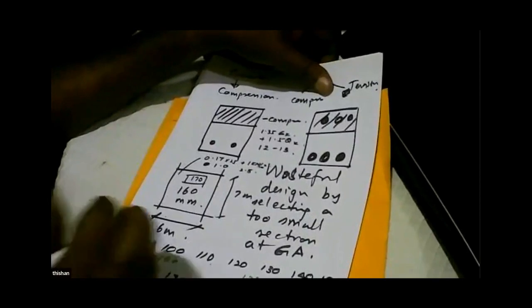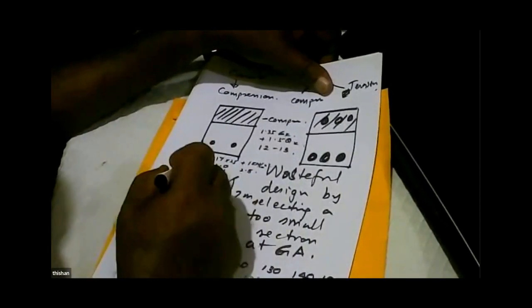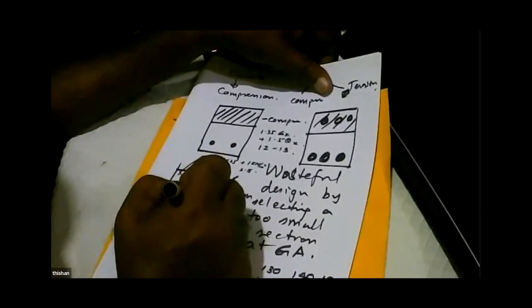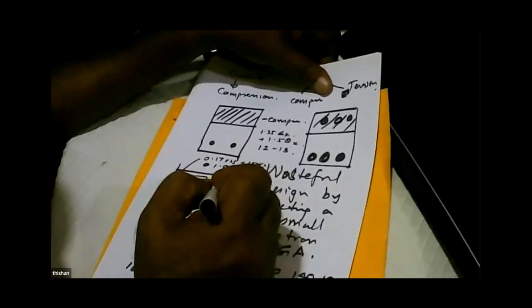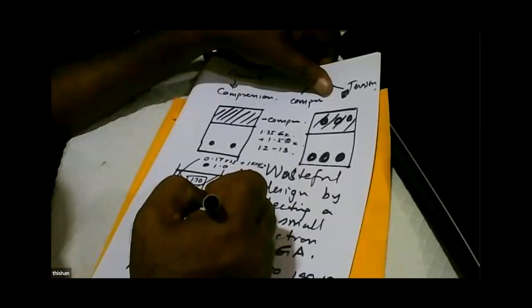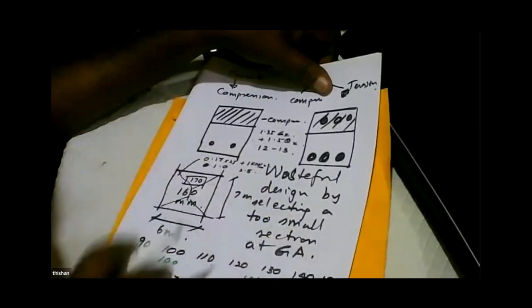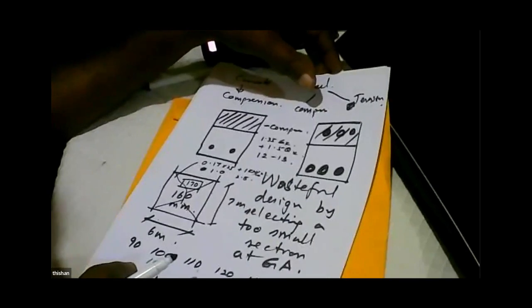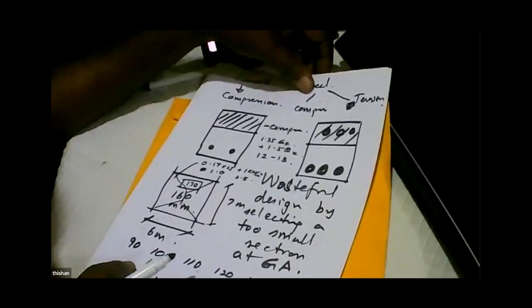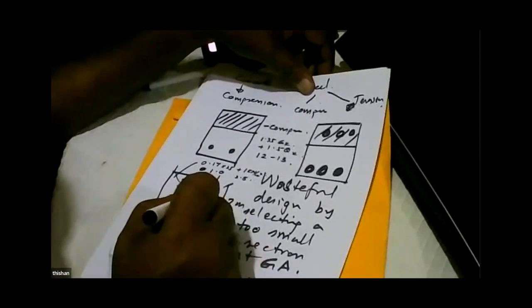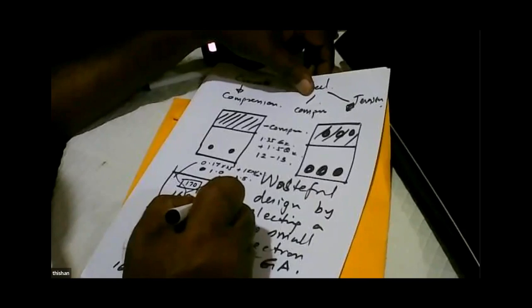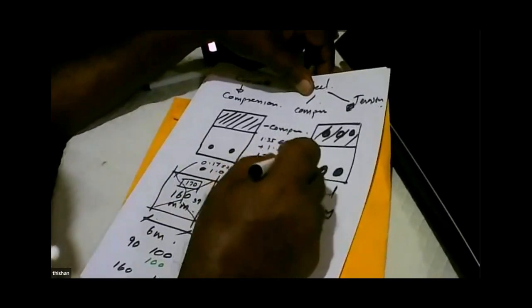So immediately you know the value 12.30, and you know in this slab the loads are going to come like this. The 7 meter side is going to get more load. So the load on the 7 meter span is 13 on this side, 13 into 3. So 39 comes from this side, 39 comes from this side. So I have considered this value as 13. 1.35 GK plus 1.5 QK is 13.